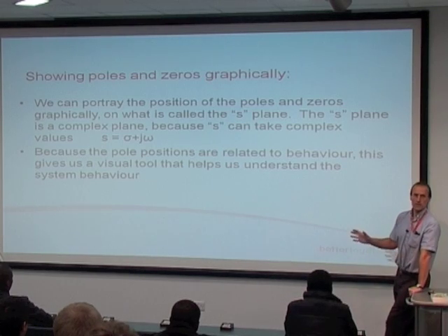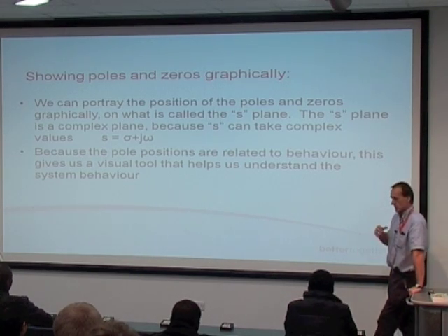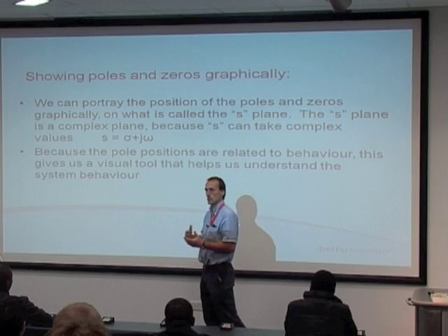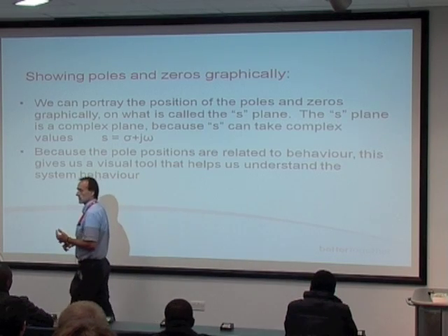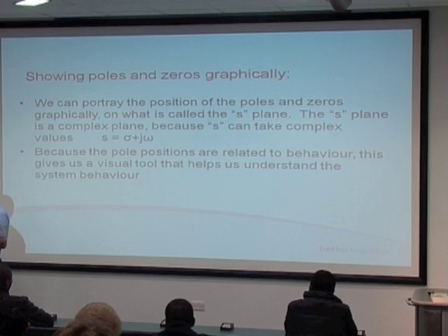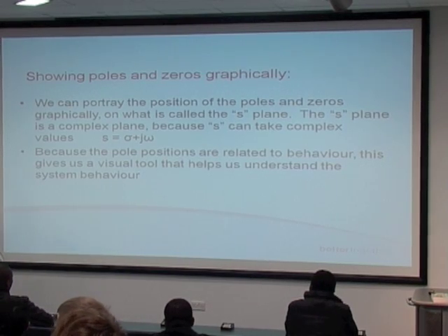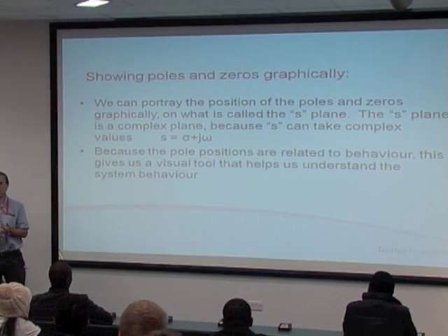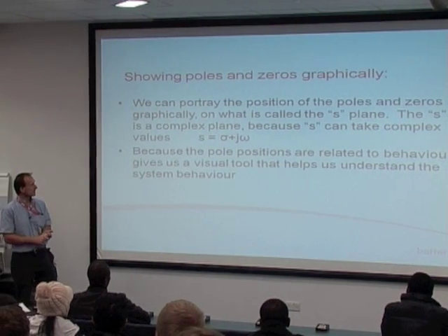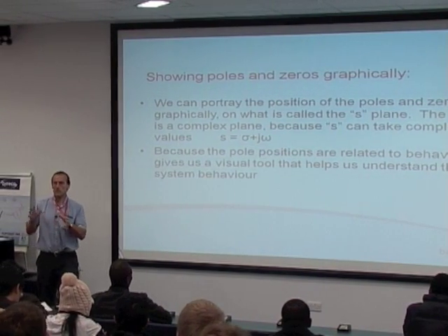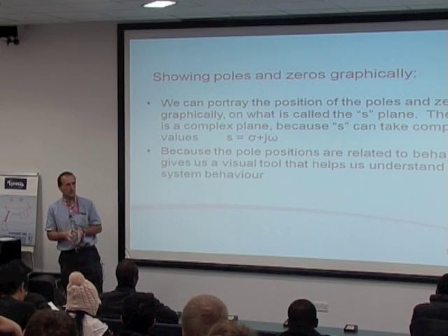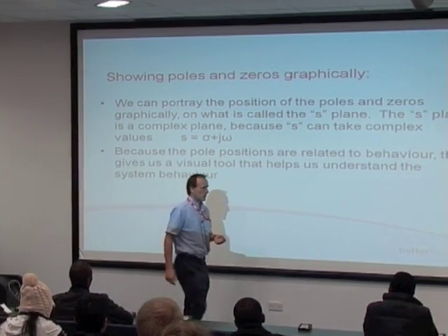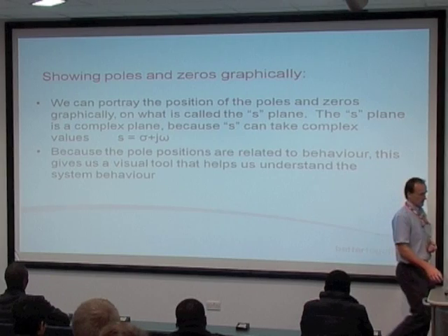That's the theory. Does it make sense so far? We've got these things called poles, and in a first order sense, they're related to time constants. If you look at the behavior of a quadratic or second order system, and you look at where the poles end up, they're also related to things like omega n. In fact, omega n and zeta, that information comes out. So if we know where these values are, and pop them on a piece of graph paper, if we can interpret that properly, we can tell what the system performance is going to be in a dynamic sense.